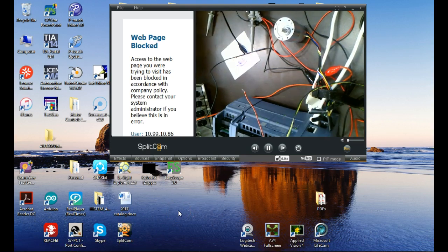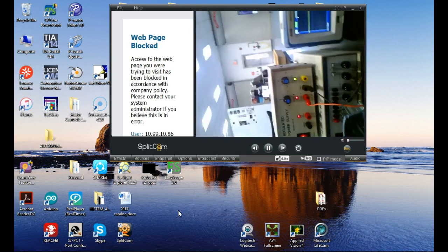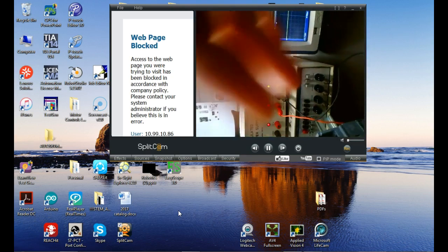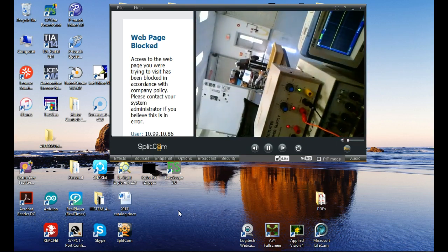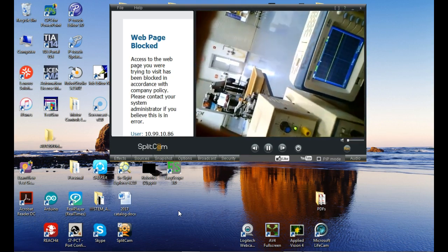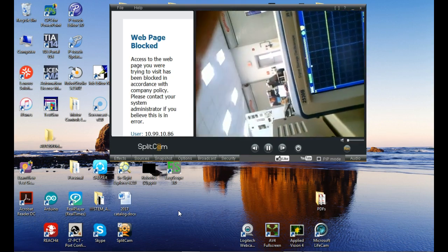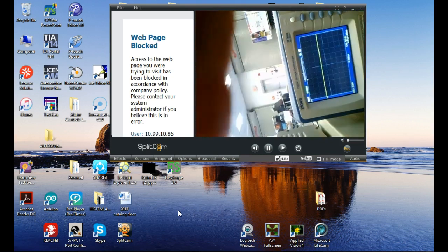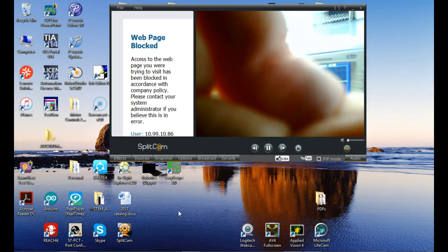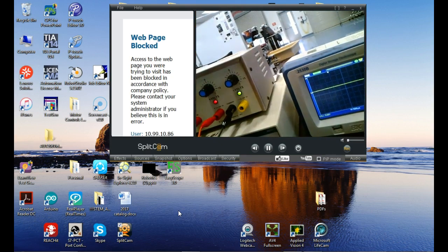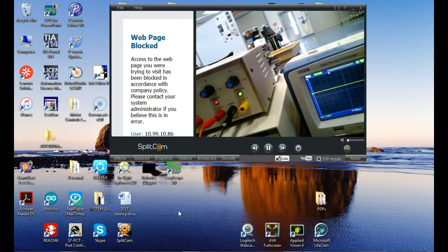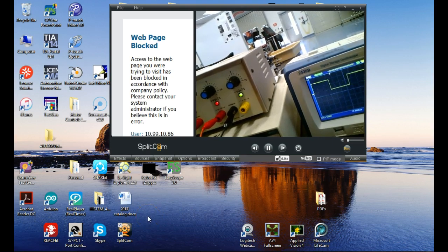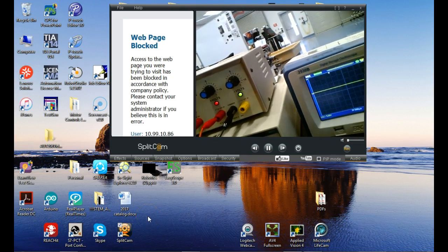I'm going to try to put both of them up here. So here's my oscilloscope. I'll try to get a little closer. And so here's our encoder. This is what we call channel A. And let me trigger on that, guys. So let me go to the trigger menu.